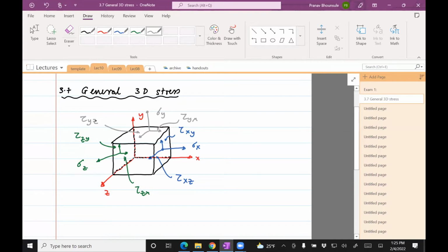Okay, so it's kind of cluttered with 3 stresses, but you have to draw that for each of the 3 which are not shown. It just becomes so cluttered. But you will essentially draw the same things, but point the arrows in the right direction, which will be exactly equal and opposite to the stress which I've shown. So for example, if there's sigma x here, there will be a sigma x in the other direction on the face opposite to the face I've shown.